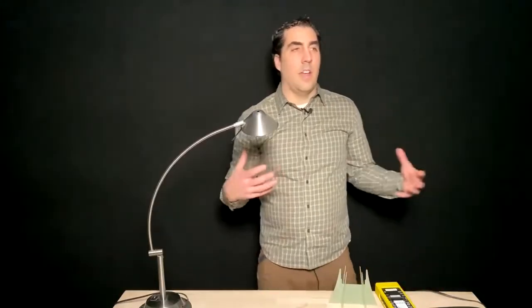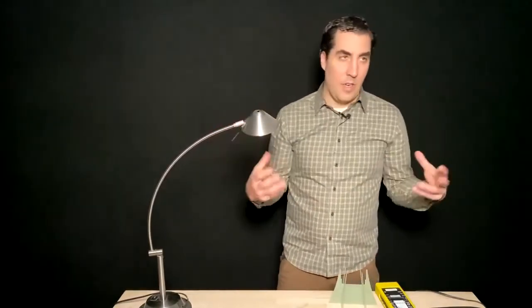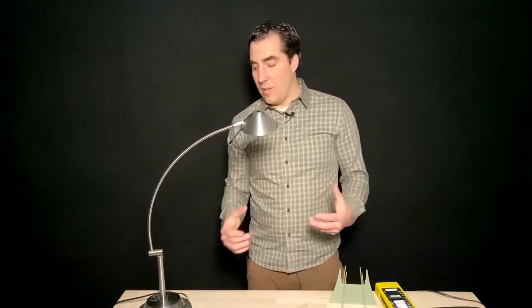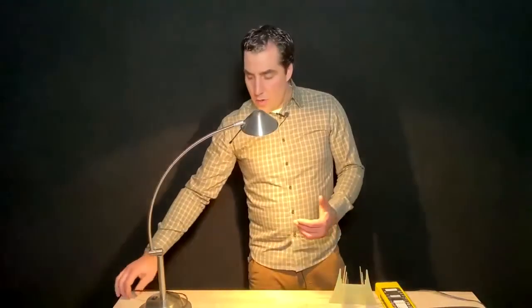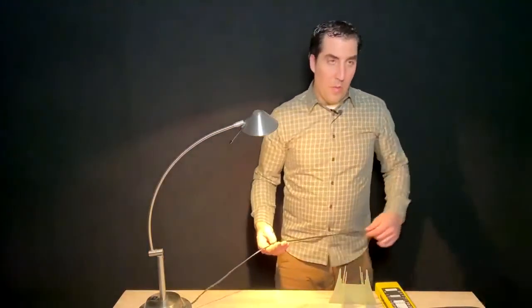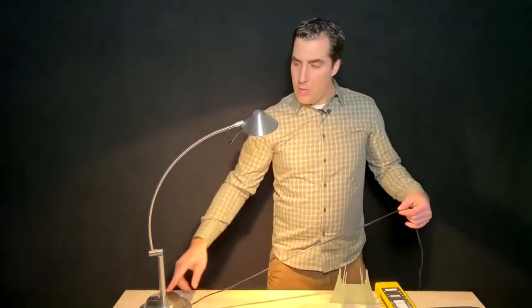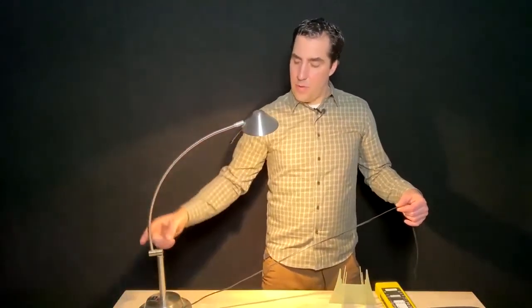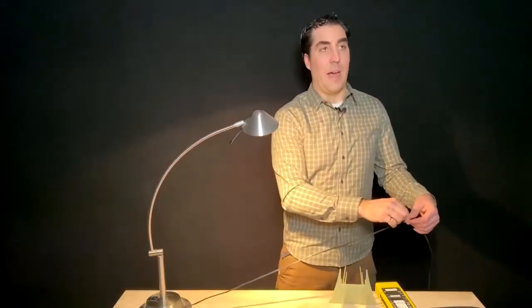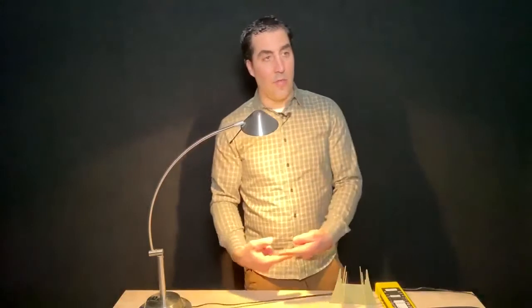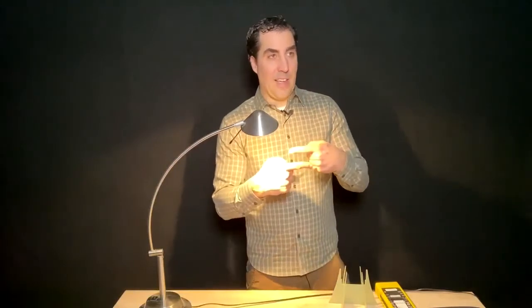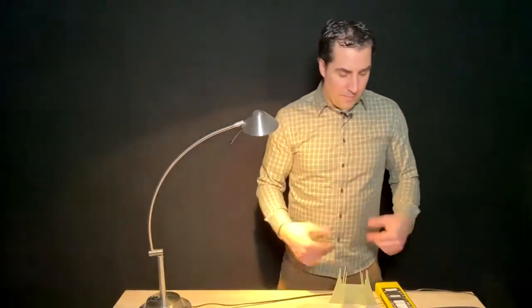Okay, now we're going to look at AC electricity and the fields created when electricity flows. So when I turn on this lamp, there's now a flow of electricity going through the lamp, going up to the light bulb, coming back down, and flowing back through the other wire. So when we have that, the current is flowing in equal and opposite directions, goes up to the light bulb, and returns back. When it's equal and opposite, there's a cancellation of something called a magnetic field.